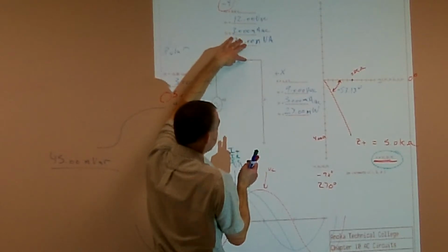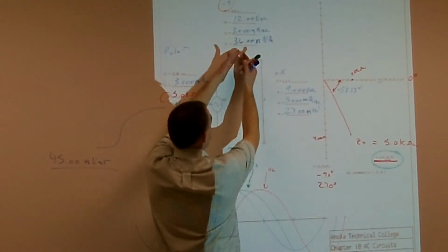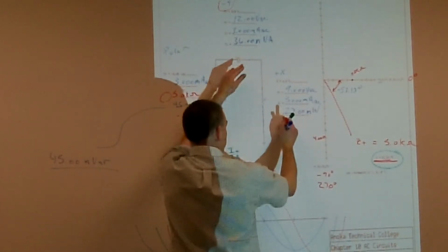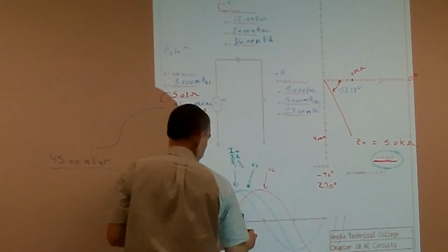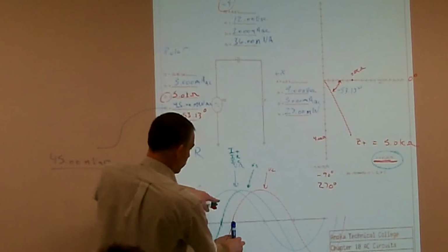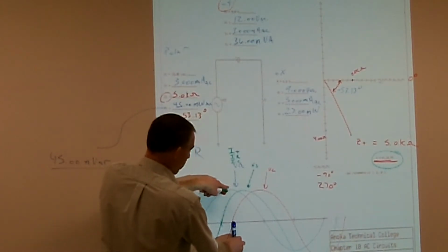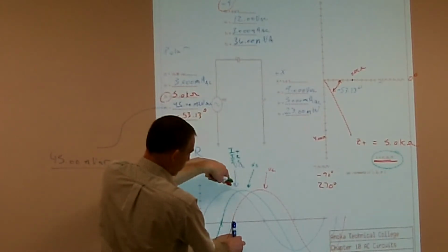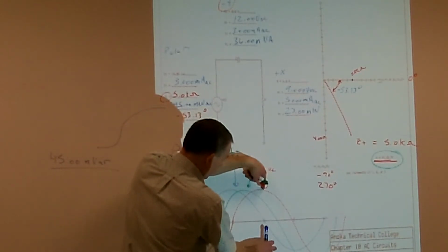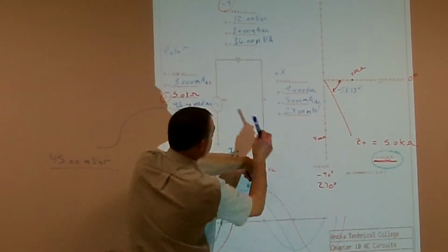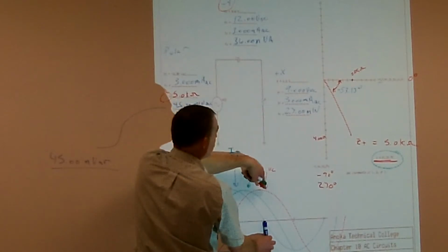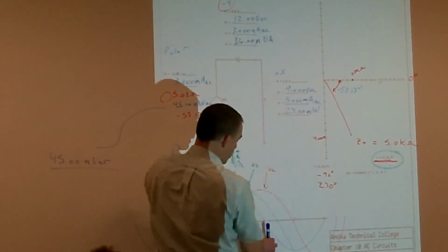When the capacitor is acting like a short, my voltage across my resistor is going to be at its maximum. So for example, when my voltage of my capacitor is at 0, when it first starts to charge up, the voltage of my resistor is at its maximum voltage. When my capacitor is at its largest, taking all the energy and ready to put the energy back into the circuit, my voltage across my resistor is at its minimum.